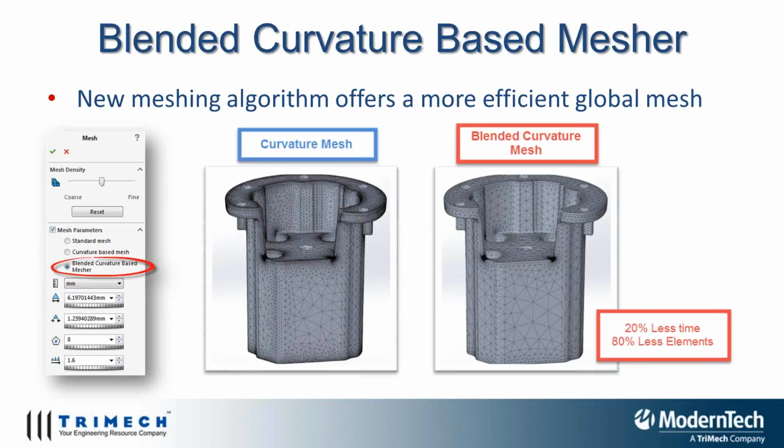The blended curvature-based mesh essentially identifies the areas of high geometric gradients and refines those particular regions while keeping all the other areas at a default or a coarse mesh configuration, which not only saves time during the solving phase, but also reduces the number of elements in the mesh. Let's go ahead and take a look at this real quick.